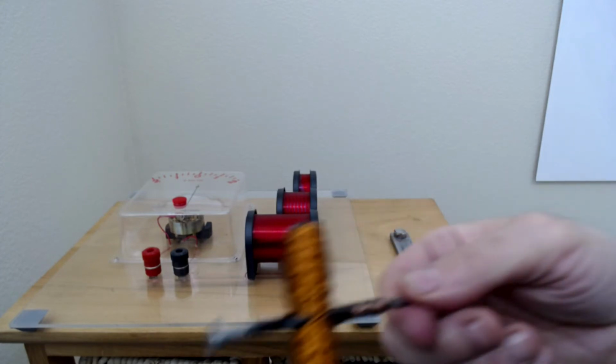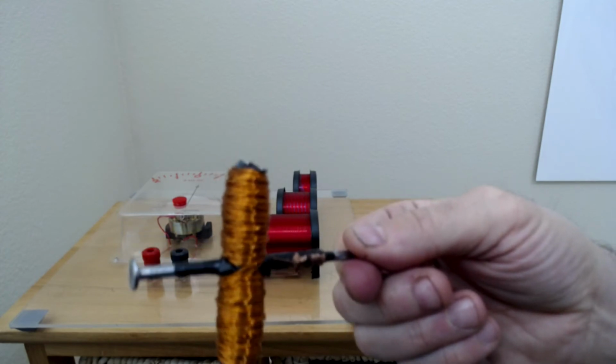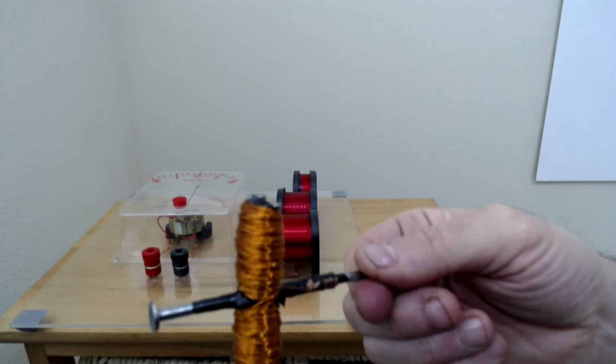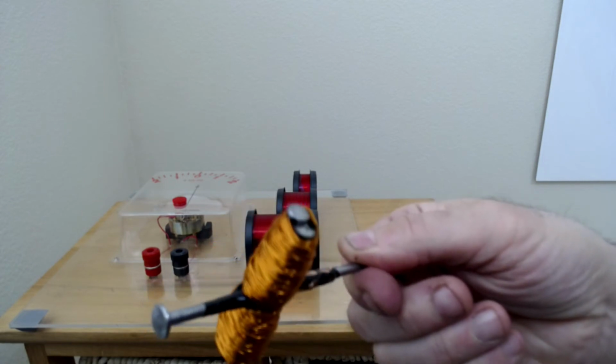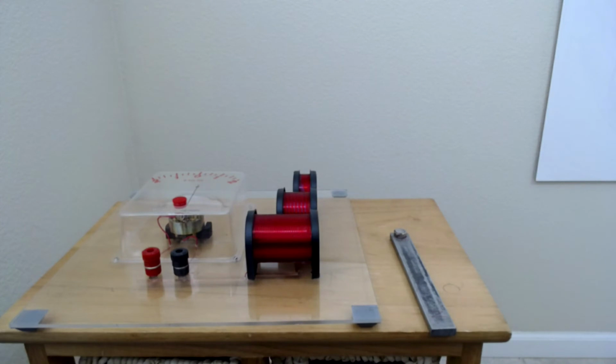One of the ways to test it is to connect the battery to it and an ammeter and measure the current. You've got to be on a 10 amp scale, by the way. Just spin this thing slowly and watch the current reading. If the current reading varies greatly, that means you don't have really good contact. And that's probably why you're having a hard time getting it to run at a lower voltage.